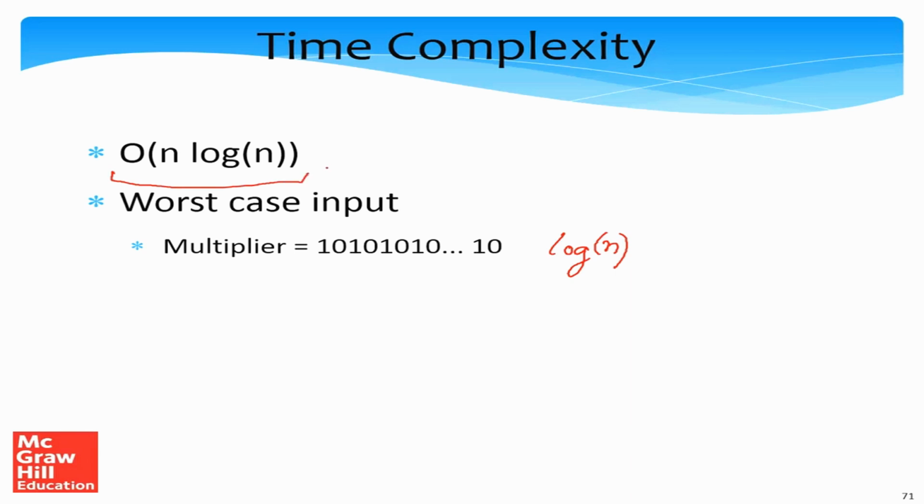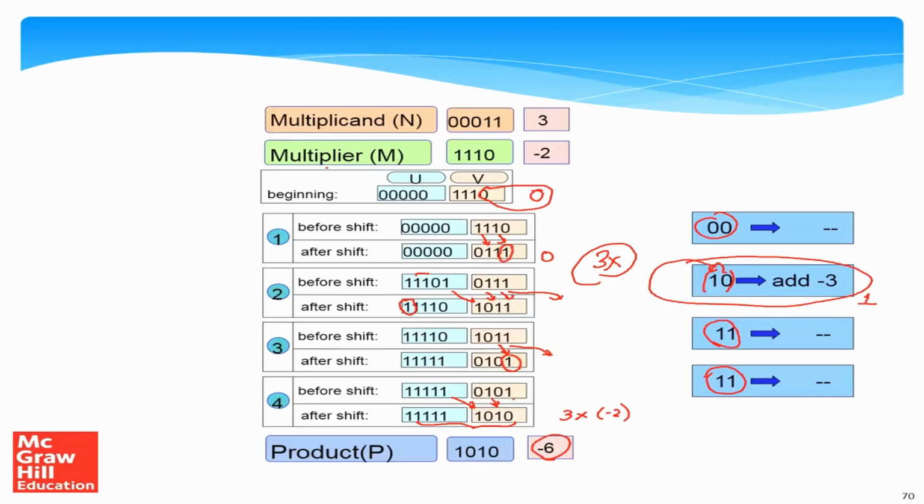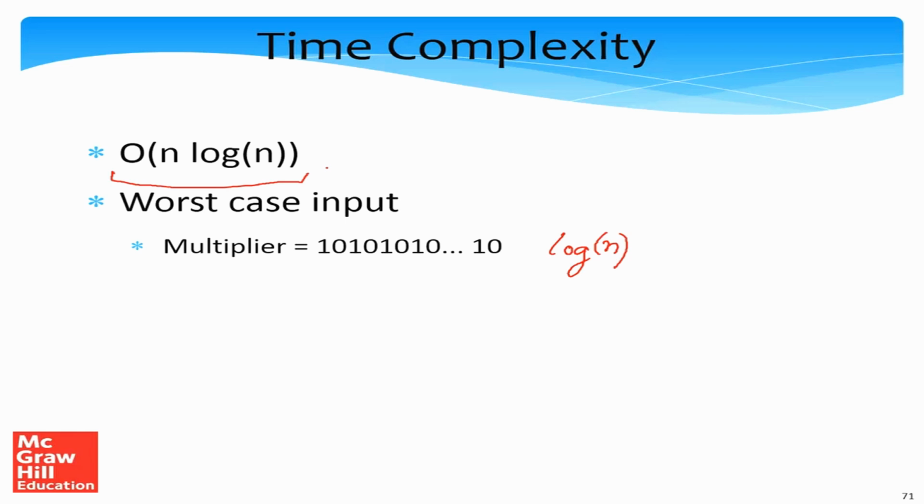So the worst case asymptotic time complexity remains the same. But in practice, we will always have numbers that have some runs of ones, so in practice we'll definitely see some speedup. This is pretty much where the asymptotic notation fails to show obvious benefits. In any case, Booth's multiplier is popular. It's heavily used, particularly in small embedded processors. That's where the algorithm finds a lot of utility.